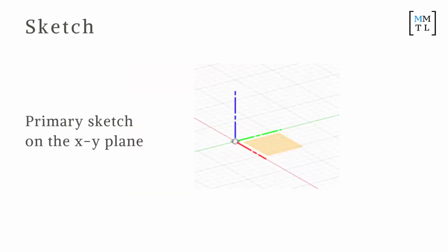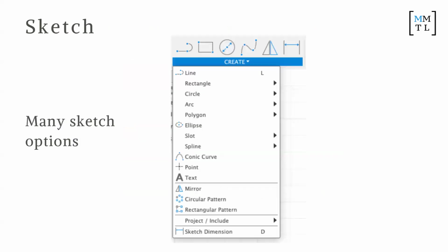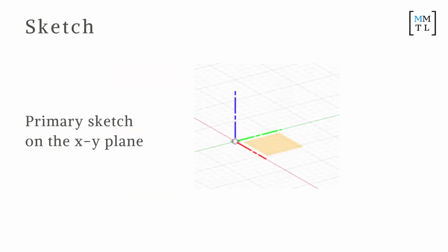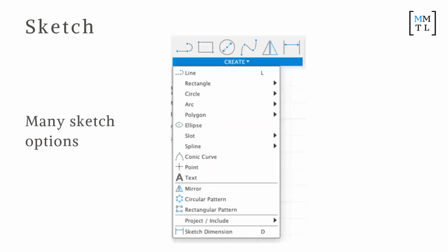Cool. So normally when we create a design, we want to sketch on the XY plane. So that's just normally the easiest way. So has everyone clicked sketch and then click the XY plane? Next one, red and green, just make sure you have something there. So this is gonna jump you into the sketch menu. And there's gonna be many different options for how to sketch objects.